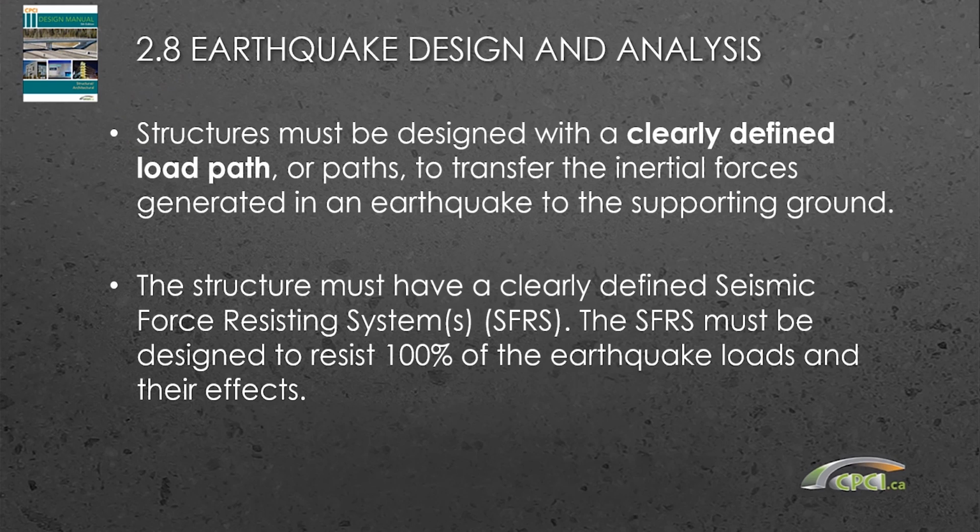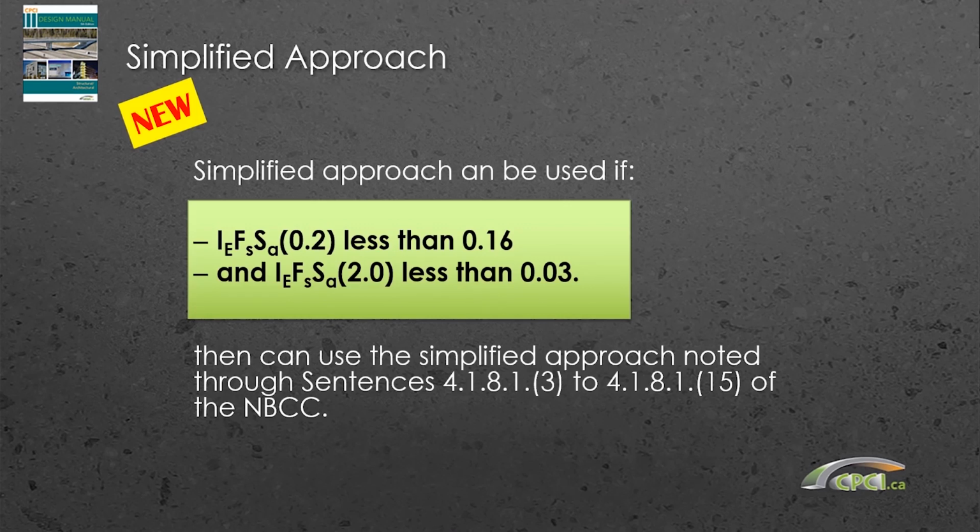Obviously, structures still have to be designed with a clearly defined load path, and you design for 100% of the earthquake load and carry that through from its point of application down into the ground. So that obviously hasn't changed, but there's a new simplified approach. Some new equations have come in. Basically, if you are designing in an area of low seismicity, you now have a simple approach that you can follow through. And one difference is the NBC now has seismic design throughout all of Canada.